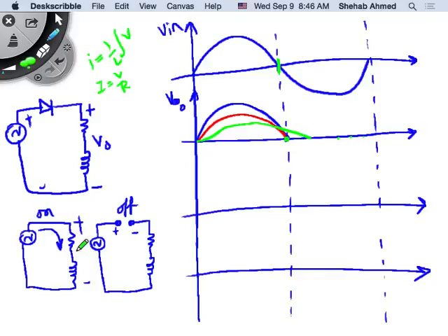You remember in your 214 course, how were you calculating the current in this circuit? It was V maximum sine omega t divided by the impedance. Was the frequency changing? The impedance was a value. The frequency does not change. So the frequency is not changing, but the value of current will change. So this shape will change, yes, I agree, because you have a certain voltage waveform and a certain current waveform. But the frequency of this component will not change.